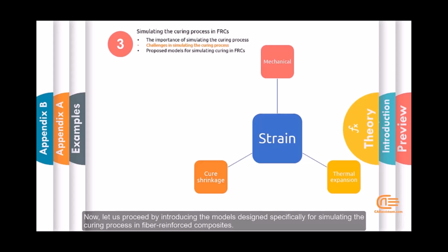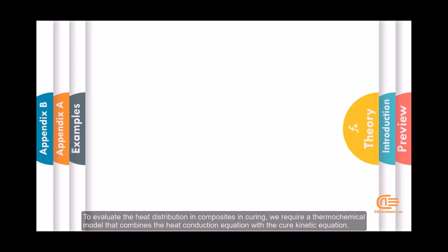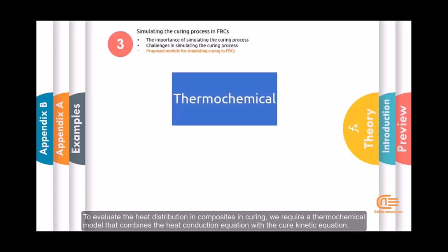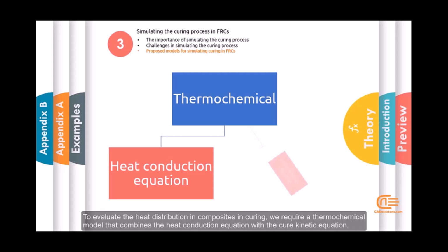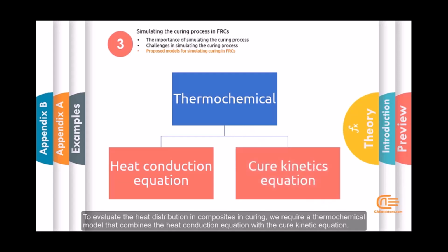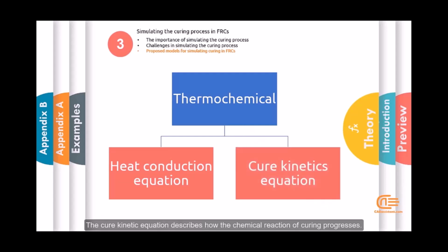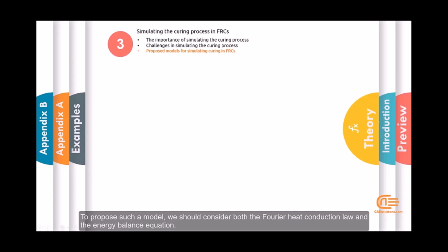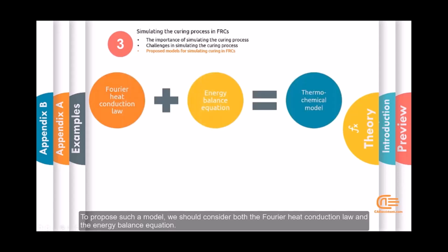fiber-reinforced composites. To evaluate the heat distribution in composites in curing, we require a thermomechanical model that combines the heat conduction equation with the cure kinetic equation. The cure kinetic equation describes how the chemical reaction of curing progresses. To propose such a model, we should consider both the Fourier heat conduction law and the energy balance equation.